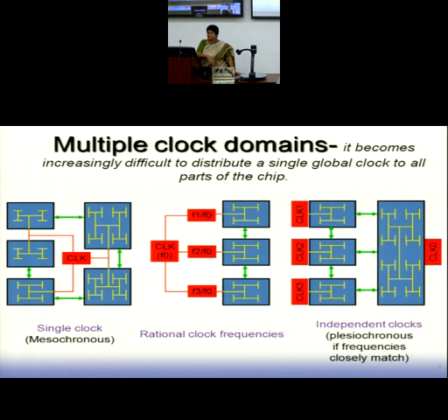This is ideally; even if it is not ideal, maybe years, 15 years, 20 years, so that by the time the processor would have aged out, I might not be using the processor at all. I hope you all have understood the problem of metastability. So here comes the need for designing a synchronizer, which is actually nothing but a D flip-flop, because whenever you feed an input, it first goes to a D flip-flop. So we are actually modifying the D flip-flop so that it does not lead to a synchronization failure.